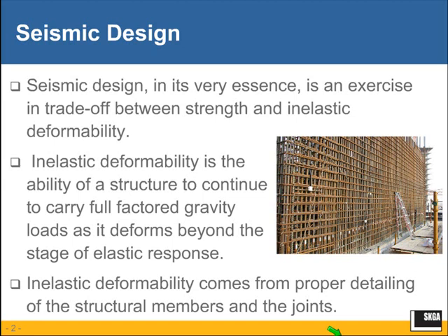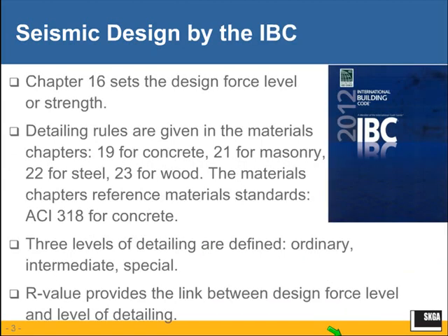Now, the inelastic deformability that we are talking about comes from proper detailing of the structural members and the joints. So in seismic design, the higher the inelastic deformability we have, because our detailing is fancy, the lower the level of strength we should be allowed to design for. The lower the inelastic deformability, because our detailing is relatively poor, the higher the need for design strength. So this is something that absolutely must always be understood.